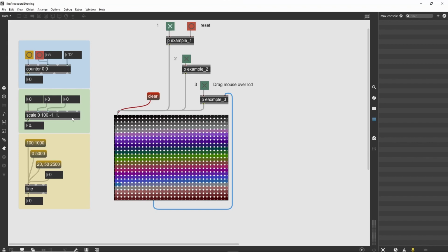If you change the input number box, you will see that a value of 0 yields an output of -1.0, a value of 50 will give us a value of 0.0, and a value of 100 will give us a result of 1.0. These numbers are mapped in a linear fashion across the range we provide. If you choose to exceed the input range, you will find that the output continues to use the calculated range effect, thereby allowing you to exceed the expected range without failing. Hence, an input value of 150 will translate into an output of 2.0, while a value of -100 will give you a value of -3.